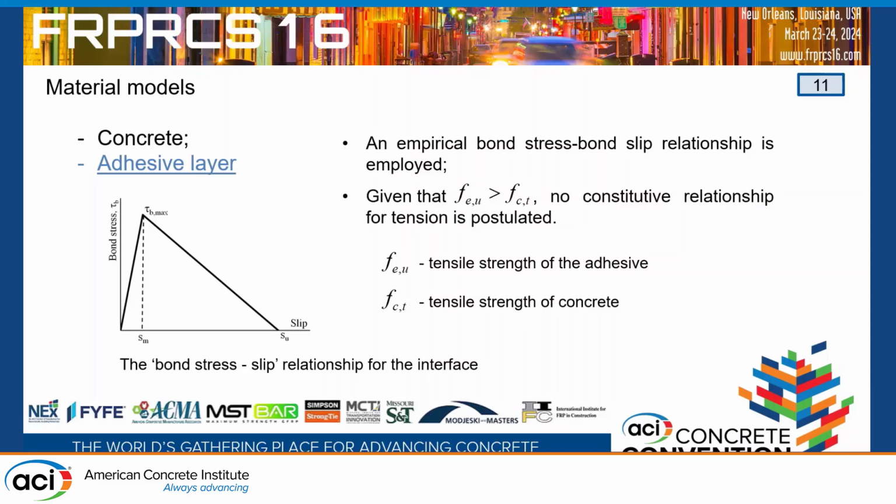For the adhesive layer, we are using an empirical-based relationship. Here it is illustrated with the simplest possible relationship, a bilinear relationship. Reportedly, the nature of the relationship doesn't matter for the overall response.